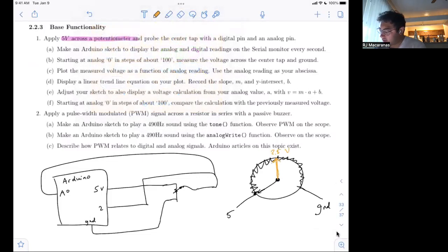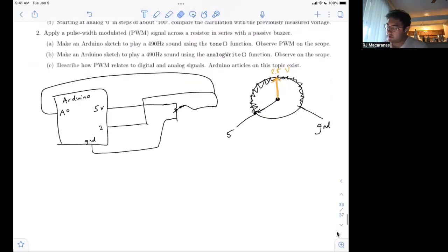I think this particular one that we have in our kit is a total of 10 kilo ohm potentiometer, right? So when we reach this halfway point, the resistance on either end is going to be 5K. And that's just interesting, kind of trivial knowledge probably at this point.